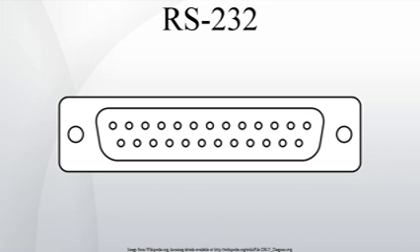Other devices may have any combination of connector gender and pin definitions. Many terminals were manufactured with female connectors but were sold with a cable with male connectors at each end. The terminal with its cable satisfied the recommendations in this standard. The standard specifies 20 different signal connections. Since most devices use only a few signals, smaller connectors can often be used.